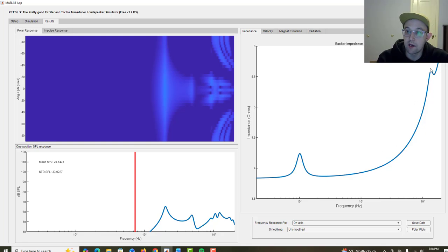And then we have another peak up here that is still a little mysterious to me, but does show up in the measurements and is due to a coupling problem, from what I understand, between the voice coil plastic and the actual plastic that attaches to the plate. So eventually that plastic that attaches to the plate is going to start bending on its own, because it's just a plate of plastic too, and that first resonant frequency is up here.